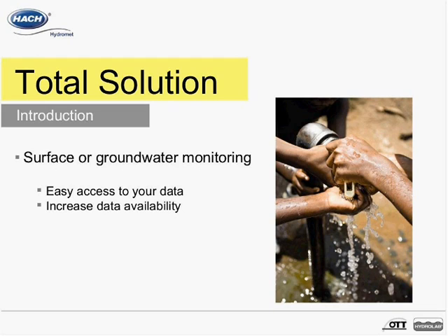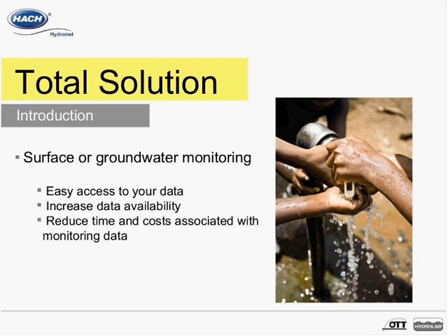Use of real-time monitoring systems greatly improves data availability and reduces total monitoring costs over the life of the project. Today we will review remote data collection as a tool to streamline data acquisition and provide access to your measurements when and where you need them. Also, we will review options for monitoring water level, temperature, and/or conductivity remotely. Later, we will take a look at flexible tools for managing your data.